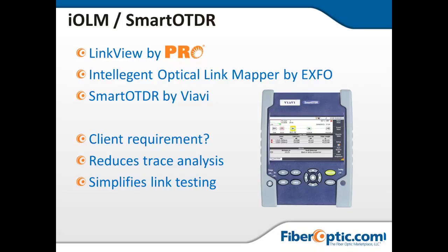And again, this Link View system was part of that OBL or poor man's OTDR that was delivered to Cablevision from the Pro solution, where they had that special process that they wanted to go through. So again, first it was the power meter reading. Second was throw it on Link View to see if it saw anything. If it did, they were supposed to go to the OTDR view to double check the analysis that came up and then go through those additional sequences of troubleshooting events. So good software. Recommend one of these solutions for sure.